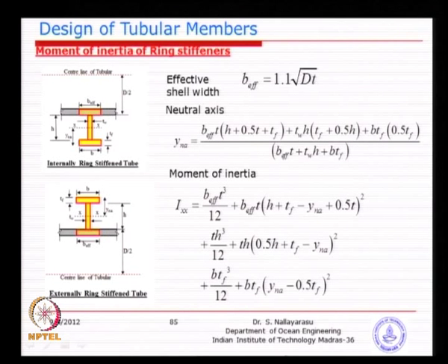without the flange. You see here, this is the flange, this is a web, this is the shell which is behaving as a part of the flange, another flange. So, you have 2 choices, either you can have this web only, or if not sufficient, you can provide additional flange. Now, this web, you are very much constrained by the thickness. If you have a 15 mm parent thickness, the web also can be maximum 15 millimeter.